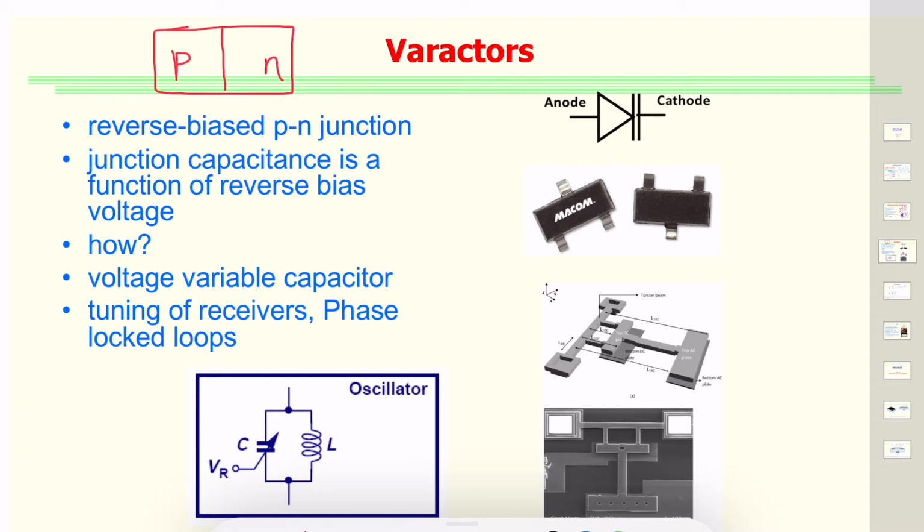But here we can see that when it is reverse biased, a region forms in the middle of those two types which has fewer charge carriers. If there are many more electrons on the N-type side and many more holes on the P side, in this region there are very few because they are repelling each other. In this part, what we have is what we call junction capacitance.